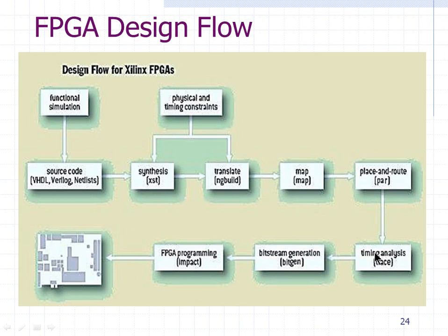You do something called static timing analysis afterwards to make sure all the timings which you are setting are met. You can set, for example, a clock. You can tell the synthesis tool that the logic that I have developed needs to work at 100 megahertz, for example. So this report will tell you whether all the paths in the design are working at 100 megahertz. There is a report that you have to read, and if there is a problem, you have to fix the problems there.